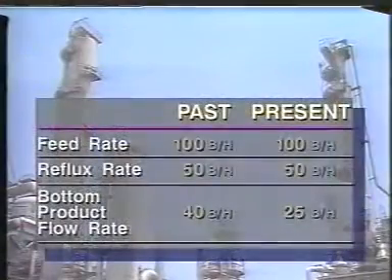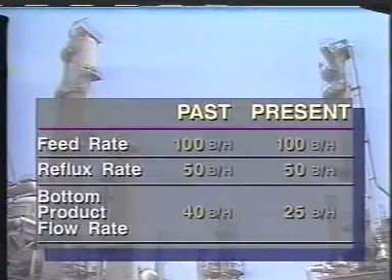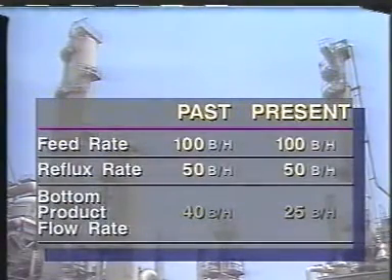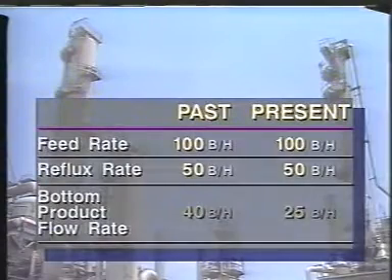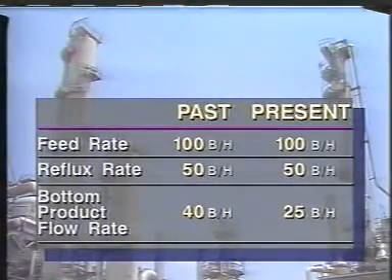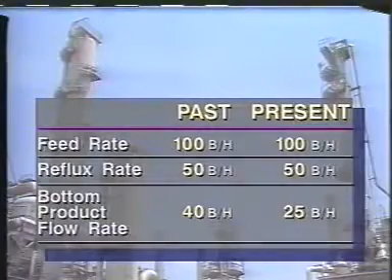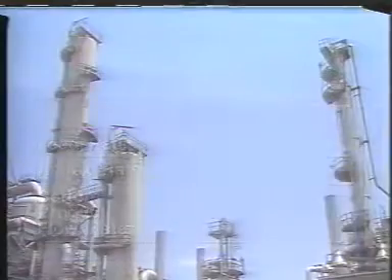You know that high levels are caused by either too much liquid entering the tower or not enough liquid being taken out. A check of the feed and reflux rates shows that these variables have not changed value. So the problem is probably not caused by too much liquid entering the column. Checking the flow leaving the tower, you find that the bottom product flow rate has decreased. The reduction in the bottom flow rate appears to be responsible for the high level.